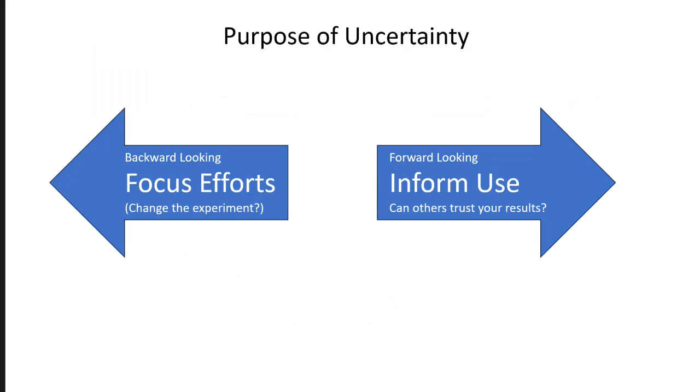And now we see that even though I've completed a non-standard uncertainty analysis, the core utility of the exercise remains the same. The analysis led to 2 physical changes in our real-world experiments, so this was a practical exercise, and my backward-looking criteria is met. Another researcher could safely apply this uncertainty and estimate to their own calculations, so the forward-looking criteria is met. Finally, I didn't waste my time nitpicking input details such as the NASA coefficients and mole fractions that would not have improved the accuracy of my results enough to change any of my decisions.